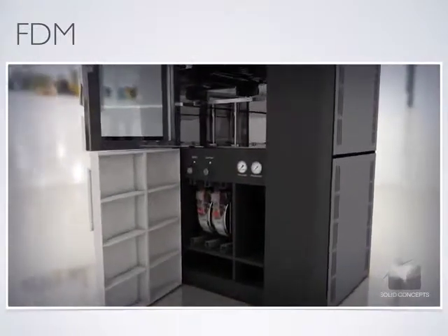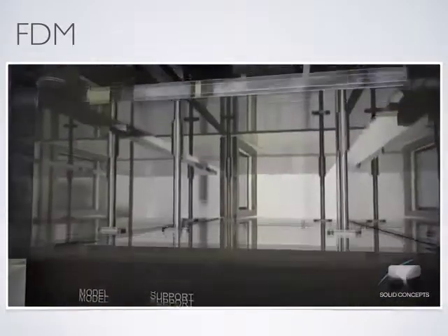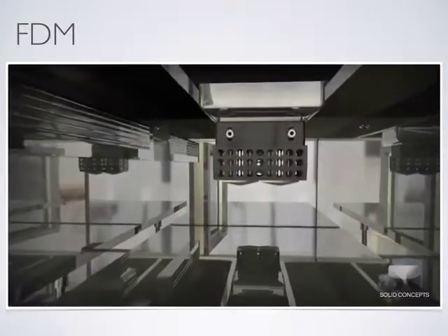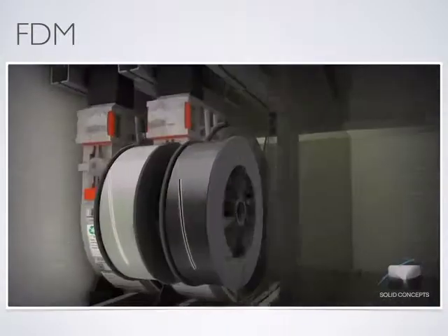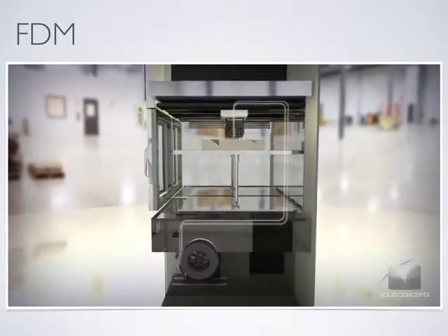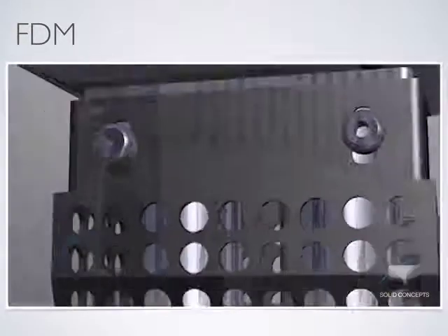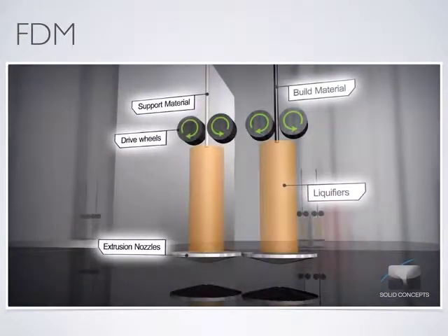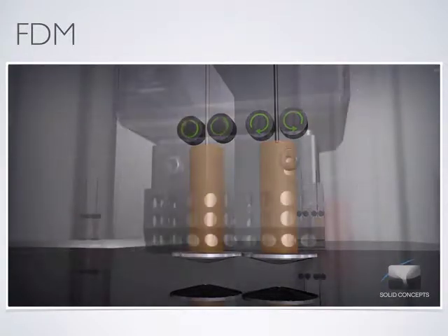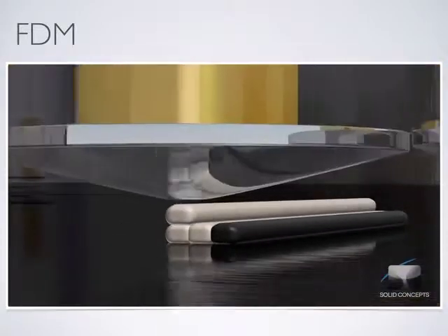The FDM process begins by slicing 3D CAD data into layers. The data is then transferred to a machine, which constructs the part layer by layer upon a build platform. Thin thread-like spools of thermoplastic and support material are used to create each cross-section of the part. Similar to a hot melt glue gun, uncoiled material is slowly extruded through dual-heated nozzles. The extrusion nozzles precisely lay down both support and thermoplastic material upon the preceding layers.